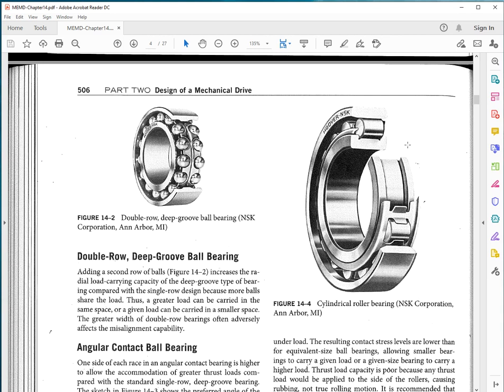They can even be separate, the outer race from the inner race with the retainer, with the cage, and you sometimes see them used as a single bearing to allow for thermal expansion, because again of the possibility of locating the rollers slightly, as we look at this figure, to the left or to the right of the outer race.